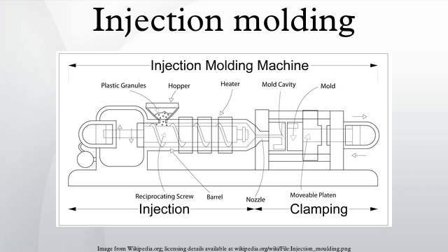The molds can be manufactured either by CNC machining or by using electrical discharge machining processes. Injection molding die with side pulls. Mold design. The mold consists of two primary components, the injection mold and the ejector mold. Plastic resin enters the mold through a sprue or gate in the injection mold.